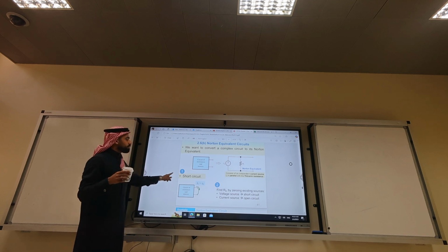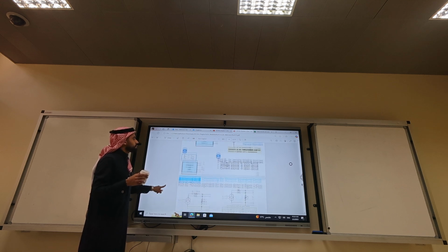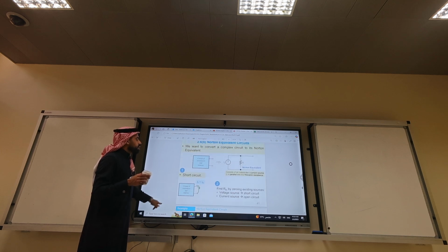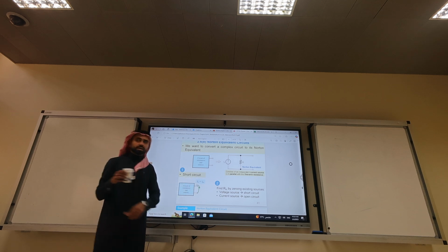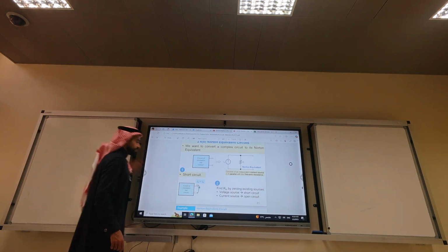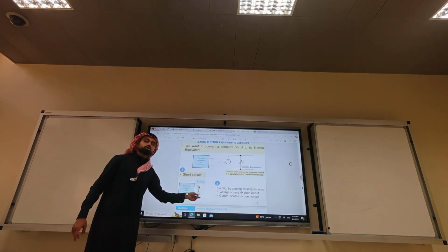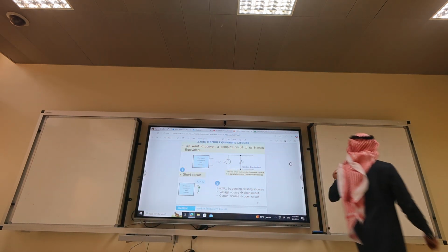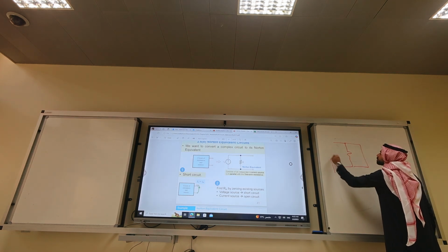There are 2 methods of finding it. I short circuit. So, to find Norton current, it's actually the short circuit current. Okay. So we need to short circuit the spaghetti circuit. When you connect a short circuit, you will naturally kill some resistors if they are in parallel. So, question in the test. What is R_AB?